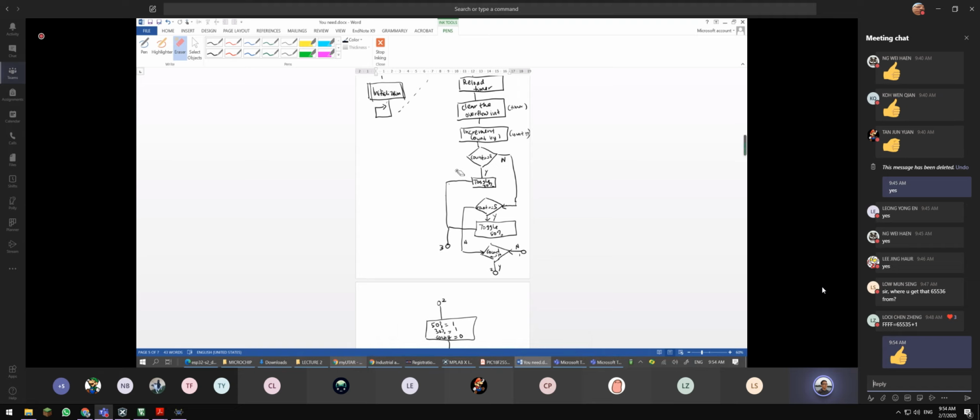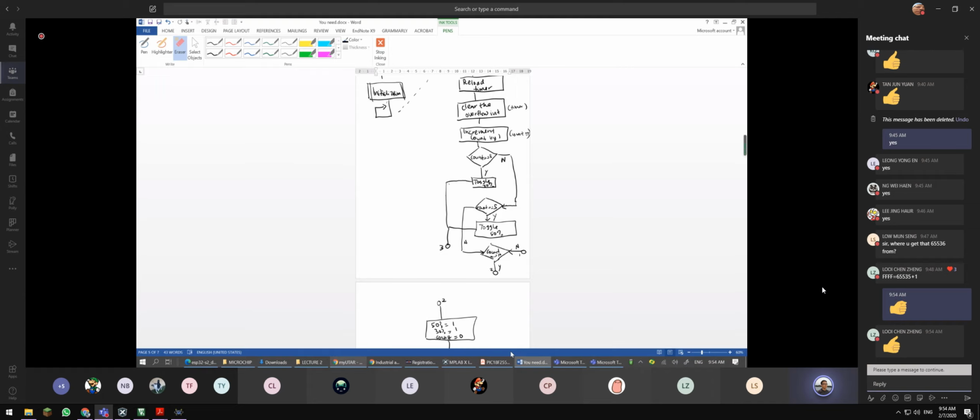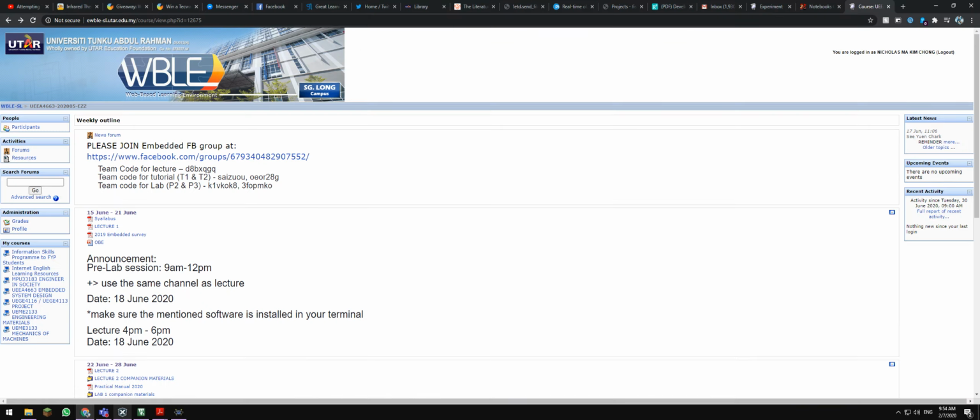Okay, there's a question where you got 65536 from. Yes, Cheng Sheng, you're very good. You answered the question for Mensing already. It's 65535 plus 1. Why plus 1? Because that is when the interrupt occurs. Because it's 16-bit, the 16-bit maximum is FFFF. So plus 1 means an overflow will occur. When overflow occurs, it will trigger that interrupt.